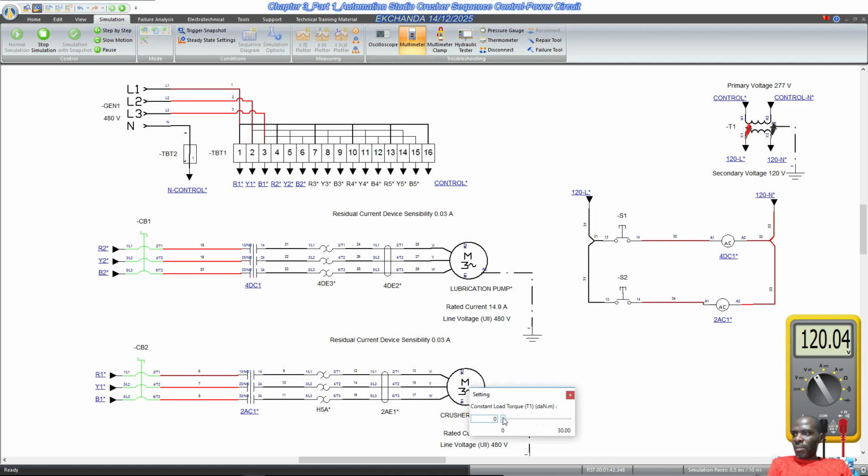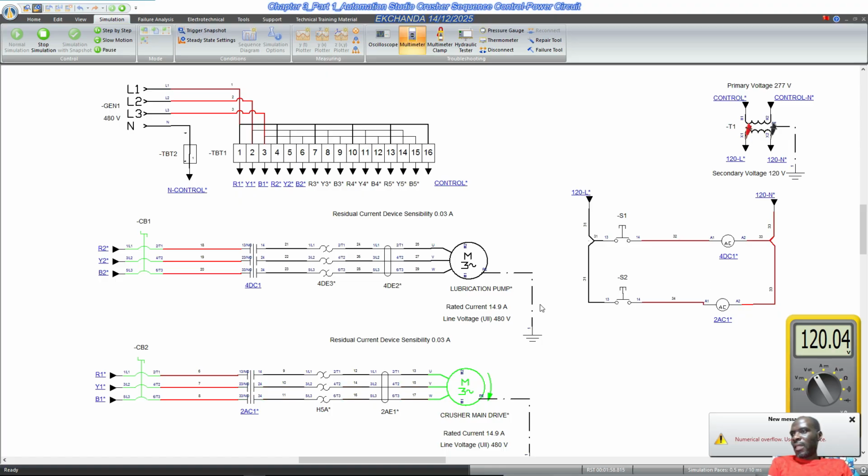We can do the same thing with this other one, okay? So control to AC1, just control this to AC1. By the way, this is the coil. So this coil and these contacts are part of the same power contactor, okay? So when we energize this coil, these contacts are supposed to close, okay? Like that, de-energized, okay? So that's the way that we hope this circuit is going to work.